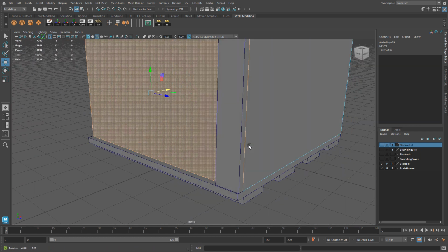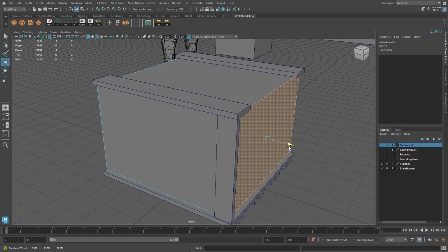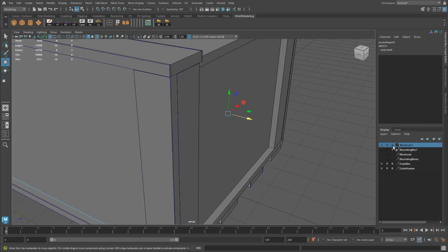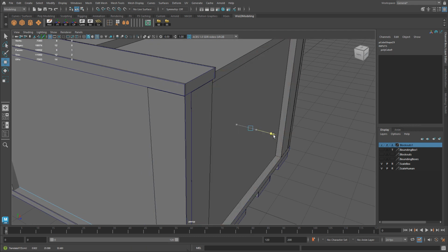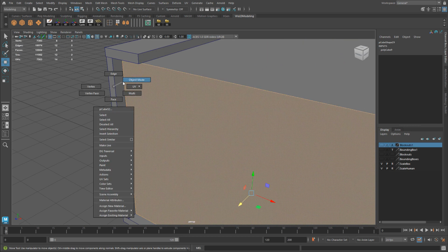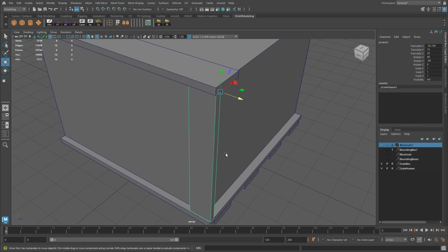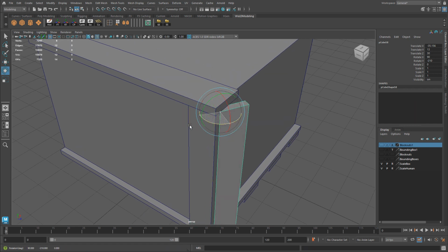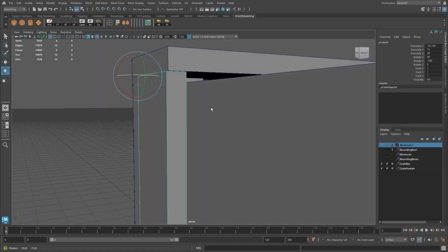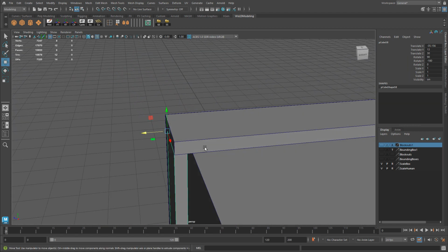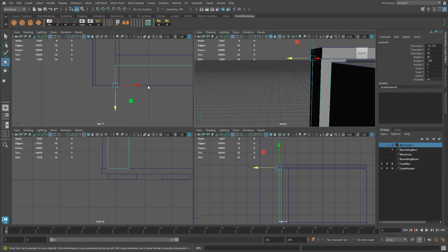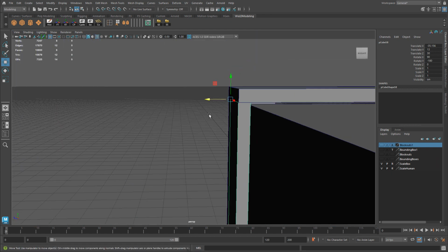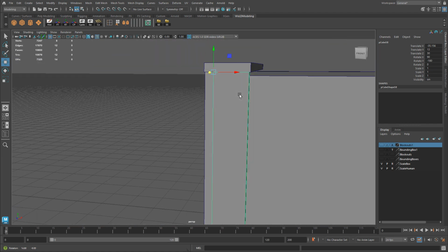Now it's completely flush. Then we need to deal with this face right here, because there's a bit of an indent. Let me turn our blackout template back on. Actually, let me set it to the reference. So there's a bit of an indent right there. We need that 2-unit indent, but I don't know how far to snap this, because the blackout is not precise. So we need to take this board right here, and I'm going to duplicate it. Control D. I'm going to rotate it 90 degrees. And the pivot point was already in that corner vertex, so it rotated perfectly. So I don't need to snap anything to that. Let me take a look at the front view. Yep, perfect. That's it for that piece of geometry.